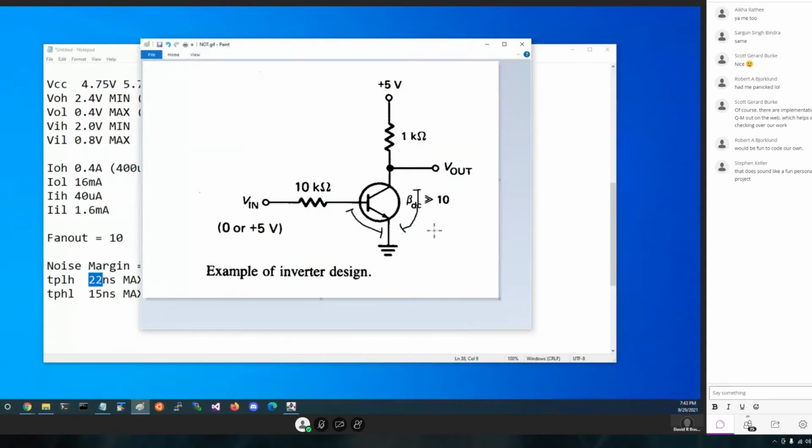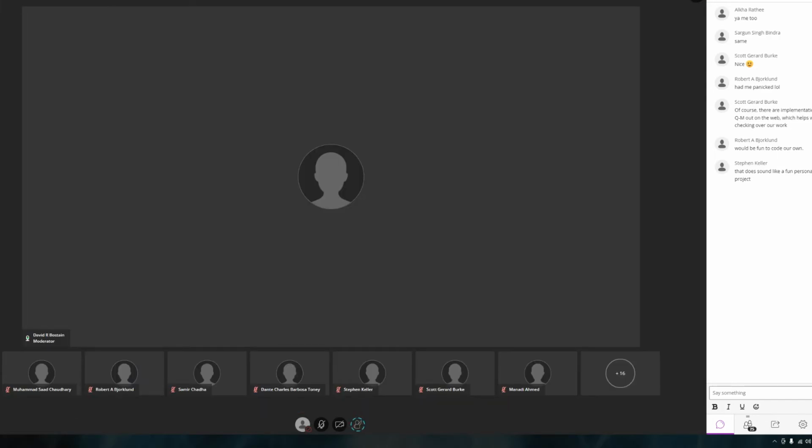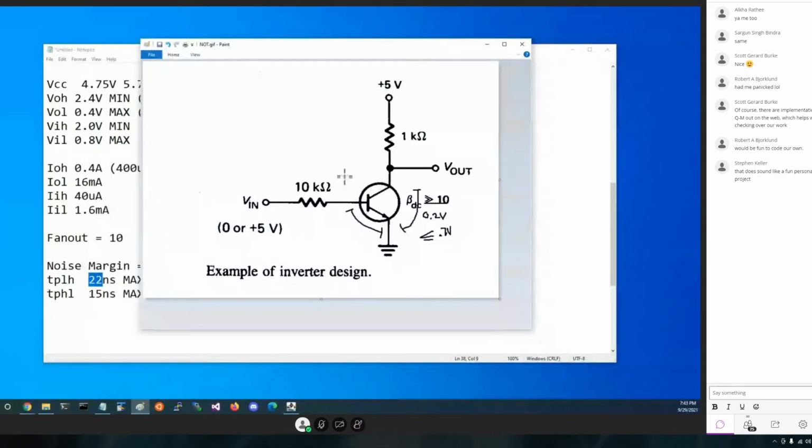Typically, we saw back on the other sheets, although I don't think I showed you the transistor data sheet last time, the type we're using, this typically will be near 0.2 volts. But all we have to say is it's less than or equal to 0.7 volts. At exactly 0.7, we may or may not be saturated, and we have to watch it doesn't change. But the way we design them is very similar to this, except they're extravagantly adding a lot more here than they need if the beta is only 10. But this is kind of what we have to think about, the idea of being saturated or not saturated. And this picture does a good job of telling us all we need to know.